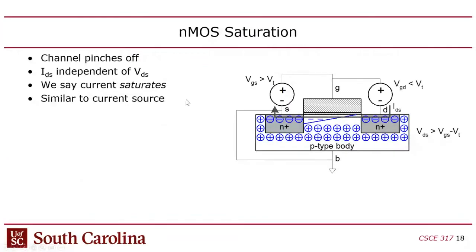Now the problem is once the voltage between the two main terminals, the drain and the source rather, gets to a certain point, then the voltage between the gate and the source, remember I said in an nMOS the source side is the lower voltage side, that may be greater than the threshold, right?